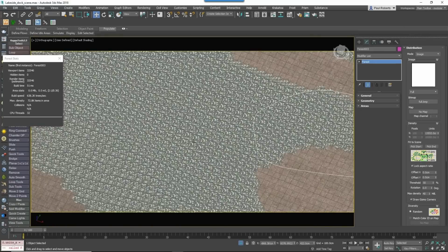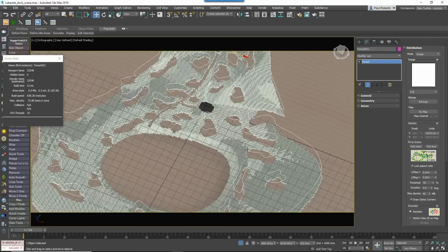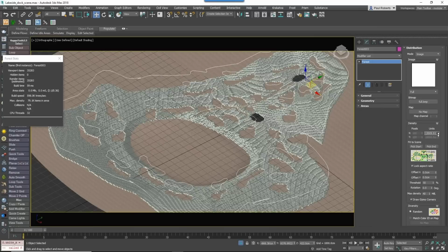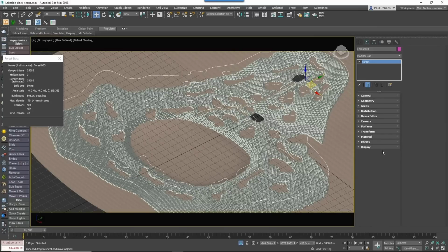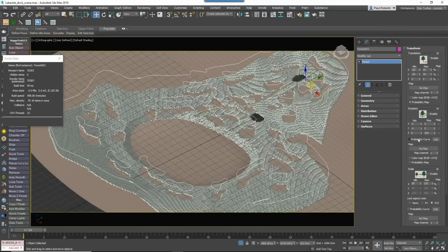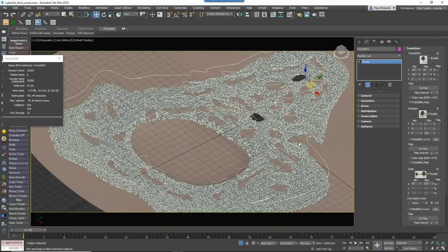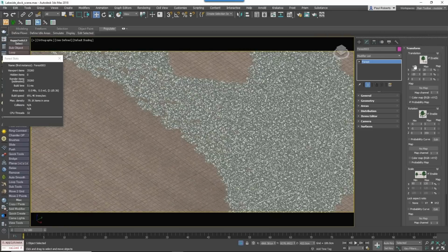Great. So we need to remove that regular grid. To do that, just like we saw with the trees, we'll go to the transform rollout and turn on rotation, turn on scale, and really importantly for breaking the grid, make sure you turn on translation randomization too. That will shuffle every patch around a little bit, and you won't get this obvious repeating pattern.